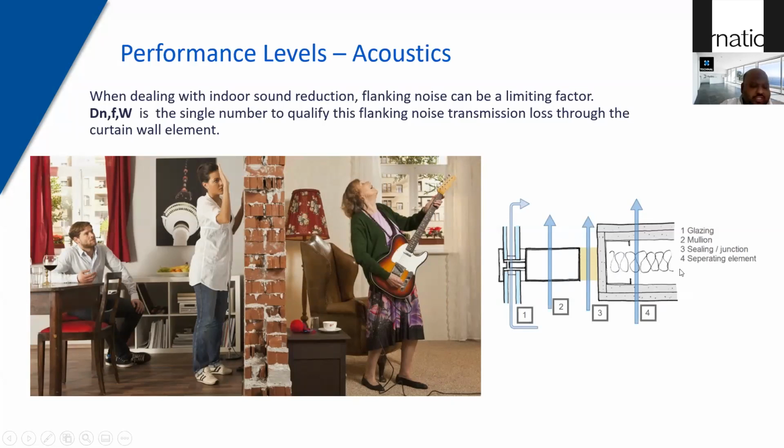So this is essentially how noise is being transferred through the wall and how the noise is being passed through the hollow mullions. This is in plan, which you see here. So noise can pass through, of course, the glass, can pass through the hollow mullion, can pass through the fire stop, and can pass through, of course, your drywall system or partition system, which is really separating between rooms.